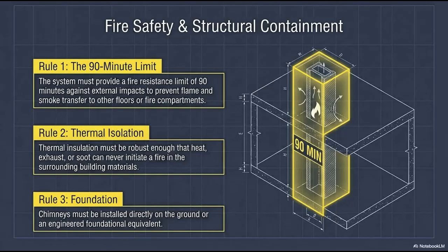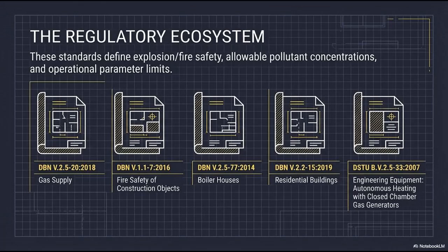Exactly. This has been a truly fascinating progression to trace today. We started by looking at how these machines evolved to breathe, from the primitive Type A appliances doing cardio in a drafty closet to the fully isolated Type C scuba divers. A huge leap in engineering. We unpacked the dangerous paradox of how our modern, perfectly weather-stripped renovations are literally suffocating older boilers in a vicious tug-of-war for oxygen. We witnessed the architectural showdown between old brick heat sinks sweating acid and modern metal flues. Right. And finally, we arrived at the brilliant coaxial heat-exchanging design of the LAS systems. It completely shifts how you view the infrastructure hidden behind the drywall.